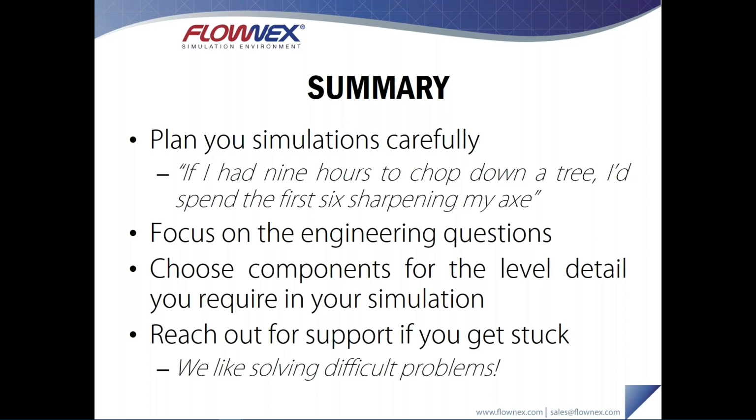Model only what's necessary. So consider what engineering questions you would like to answer, and then from there, make decisions about exactly how you should model the system, exactly which portion of the network is important to model. And then also choose components relevant to the level of detail that you require.